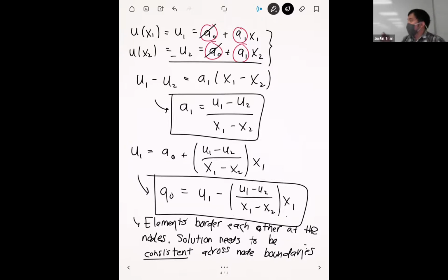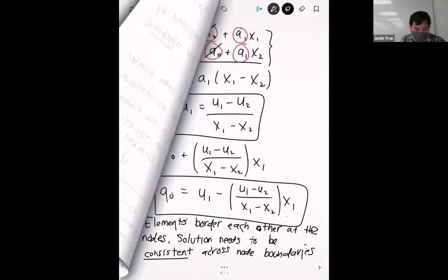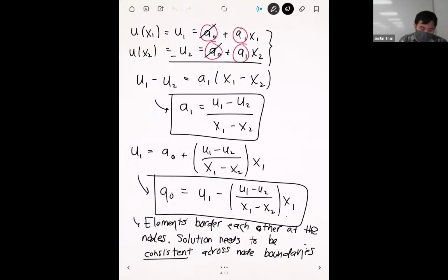So that's a little bit of a deeper look into what's going on with the element order and why the cost goes up when you choose quadratic. For a quadratic element, compared to the 2 nodes in a linear element, you're going to have 3 nodes. You have node 1, node 2, and the node that's in the middle is given the higher number, so that's node 3. For quadratic elements, and you'll see this for 2D and 3D as well, the additional nodes are placed in the middle of the element, usually at the middle of an edge, basically where it can be shared with the neighboring element.